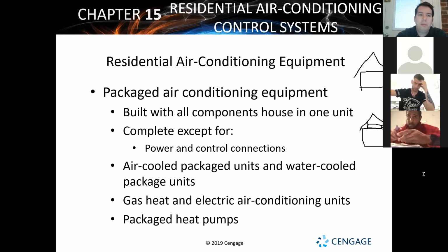Package units, typically the main reason why they're not used residentially is space. Most residences have it where you can access the ductwork inside of the house. Because of this access, you can fit an air handler inside, you can have a technician work on that, and it makes life a little bit easier, because all you have to worry about outside of the building is a small condenser unit. You don't have to deal with a very large package unit. This package unit usually takes up a lot more space outside of the structure.